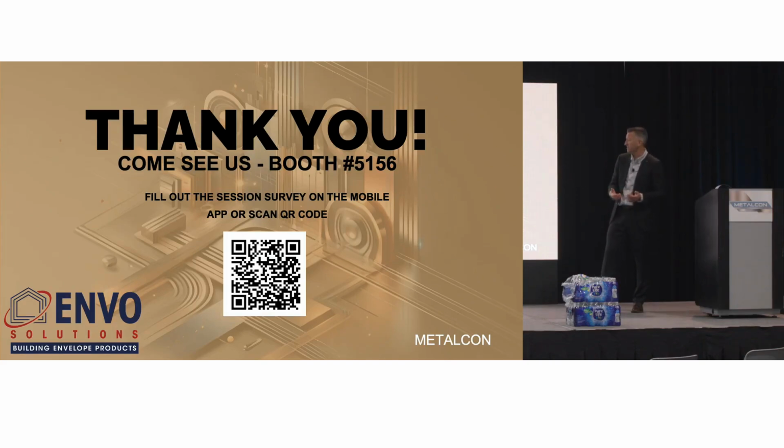Made me think of something I completely forgot. You cannot go to one of the big box stores and buy green rigid insulation and put it in your building. There's a very big difference between the 2 manufacturers that I mentioned, R-Seal and Thermax, because they are fire rated as Class A materials.